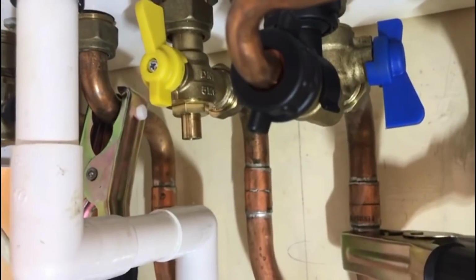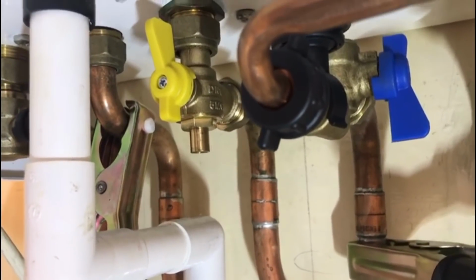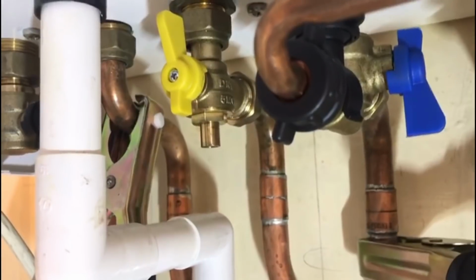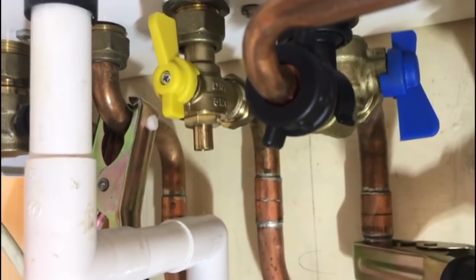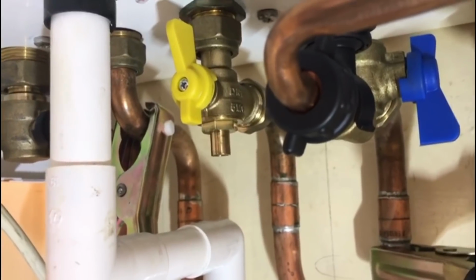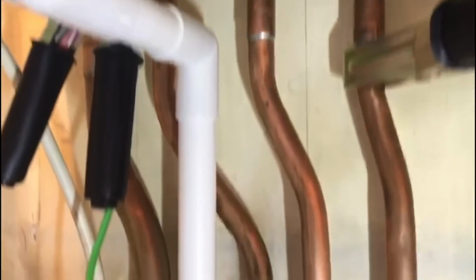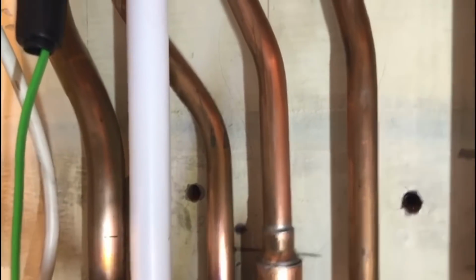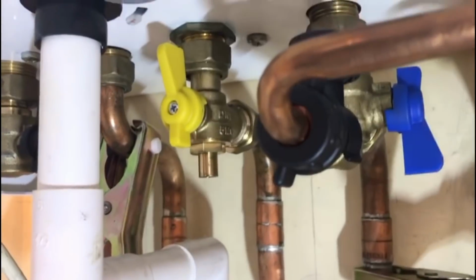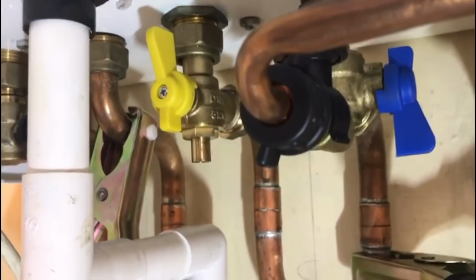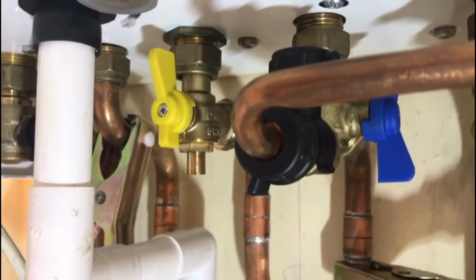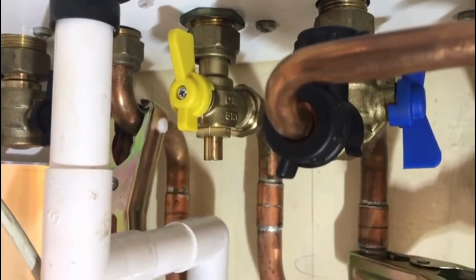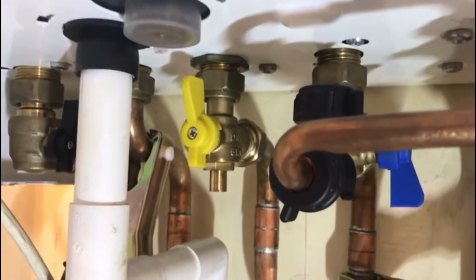Now you need to get the temperature clamp on the hot water as close to the exit of the boiler as possible, purely because as soon as the hot water is leaving the boiler, it's cooling down straight away, and if you put it down on the pipework down here, for instance, you could be a couple of degrees difference in temperature. So if we get the hot water temperature clamp as close as possible to the exit of the boiler, it'll give us a better reading.